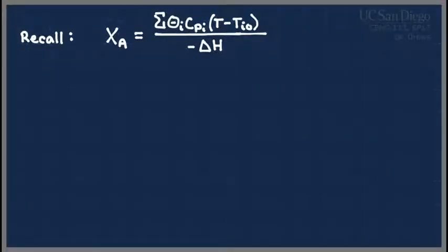And we had said that that particular form was only for adiabatic CSTRs. And generally, all those other assumptions that we have on our energy balances still hold, so no shaft work inside there, which we don't really bring up, so I don't make an explicit note of it over there, but also for a single reaction. How do you know it's for a single reaction? Because we're dealing with an X. If we write equations in terms of X's, those are almost always for single reactions. So we had said that that was for an adiabatic CSTR.